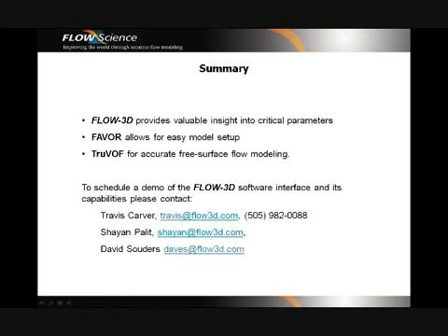And we do have one other option too. Fish screens could be done with baffles, and as long as you know the porosity and can properly define the drag effects, you could use baffles and have a two-dimensional plane that looks at this drag.